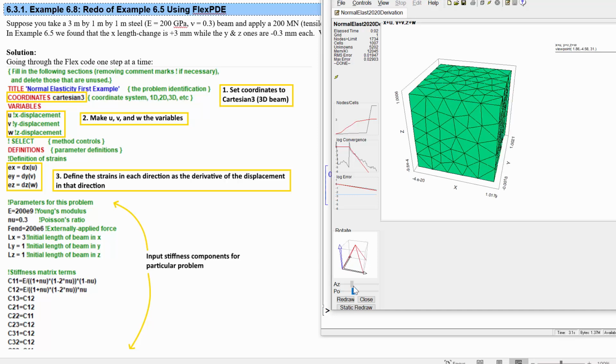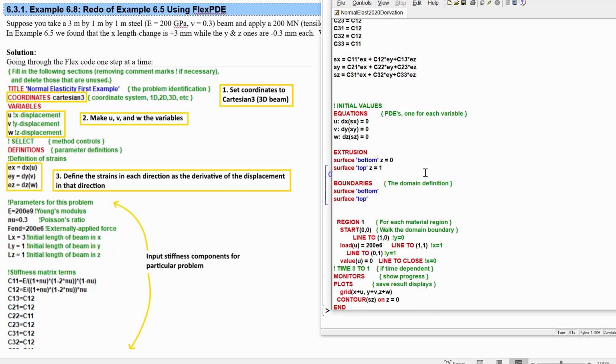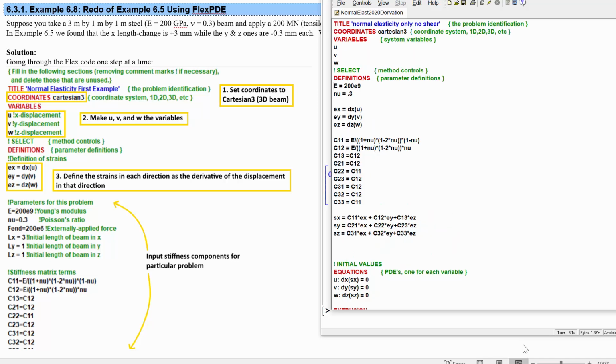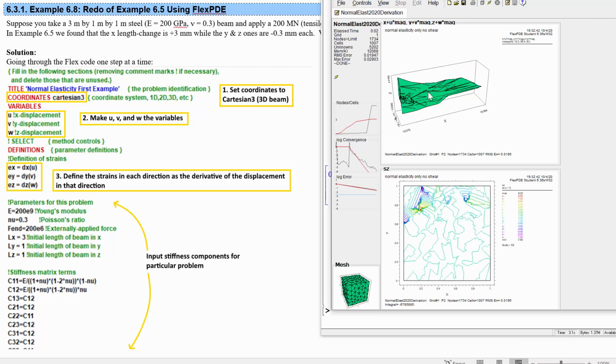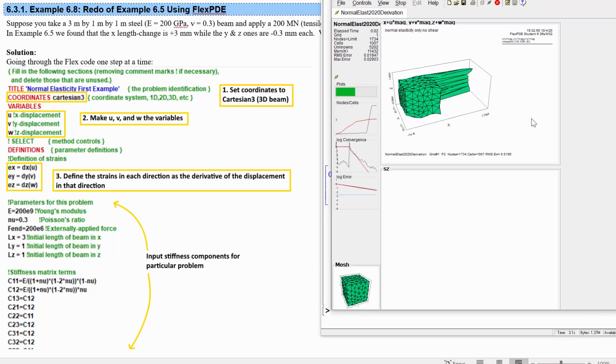This is because the stress that we're applying is not very big, right? So we need to magnify the displacement to be able to see this. And one way to do this is by multiplying each by magnification. And we'll set this parameter to 1,000. So let's look at what things are doing. Yeah, that's no good. It was supposed to move just 3 millimeters. I guess if we multiply that by 1,000, that's kind of a lot. It's sort of folding in on itself. Let's multiply it by 100 only.